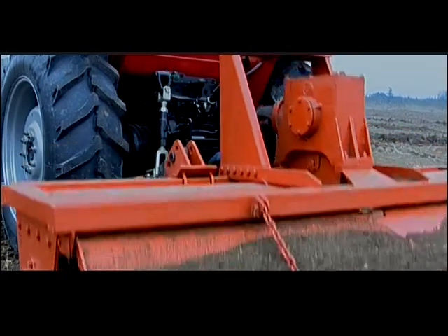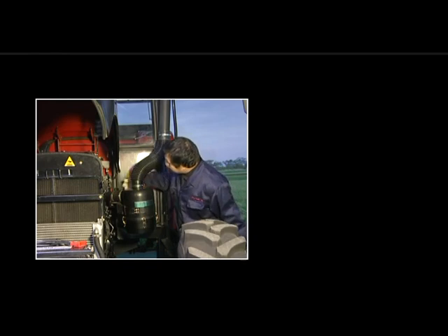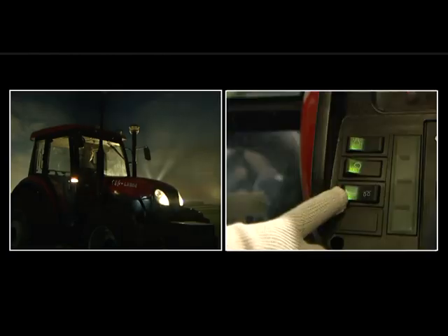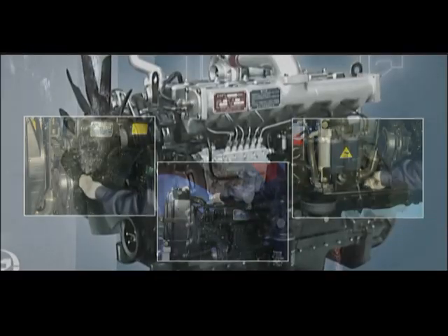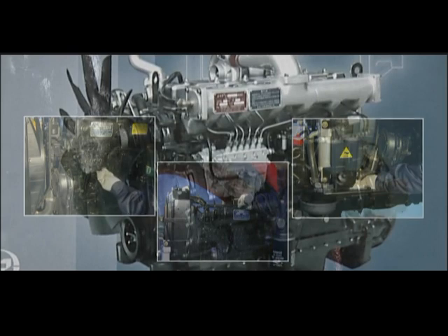Check if the lifter operating can perform in normal condition or not. Check if the tractor has air, oil, or water leakage. Remove the trouble when occurs. Check if the operation of lamp, horn, and instruments are normal or not. Maintain the diesel engine as the engine operation and maintenance manual.